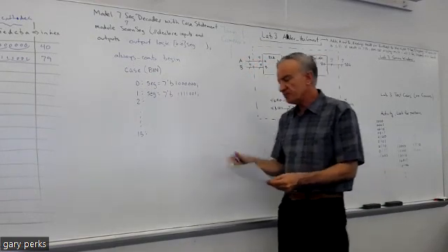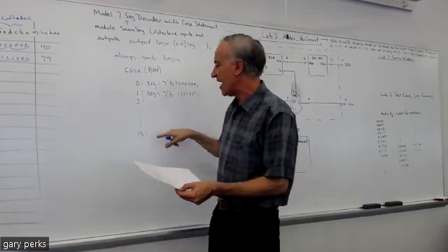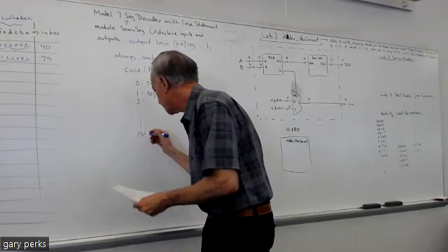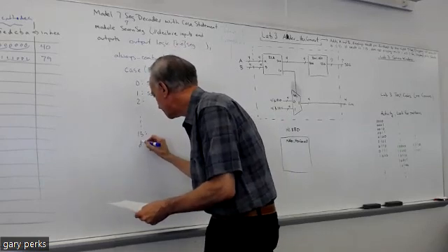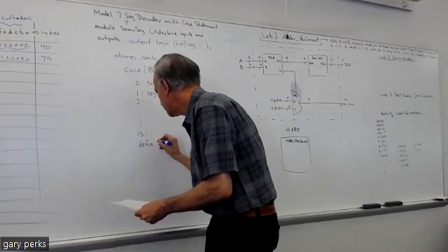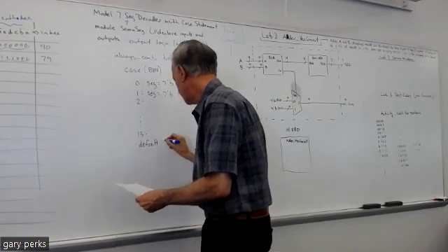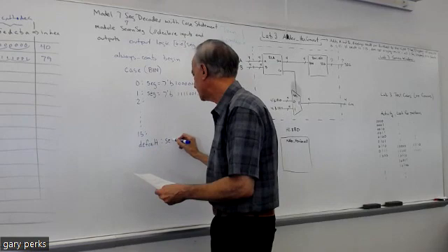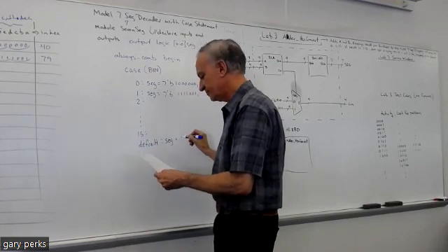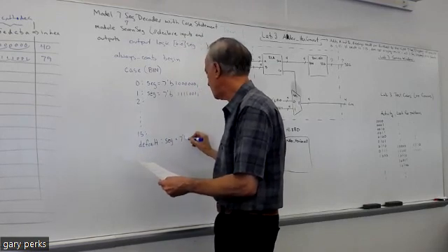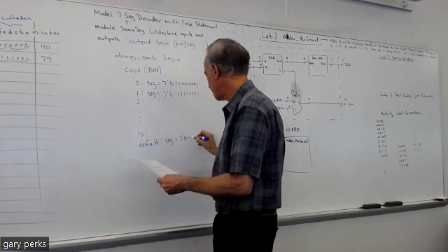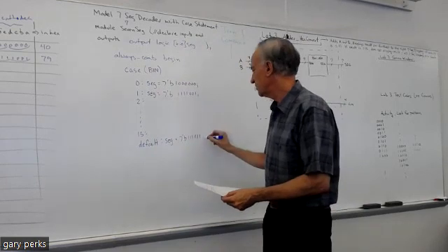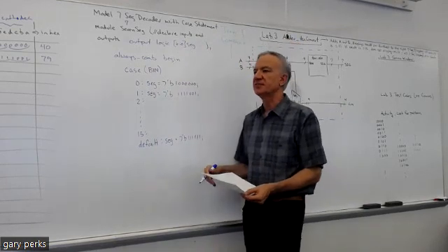Okay, now also in a case statement, after your last option, you need to put a default. So after the last option here, you would write default, then a colon, and then you would just set seg to something. I set them all to 1 just to shut off all the segments. But you can make the default whatever you want.